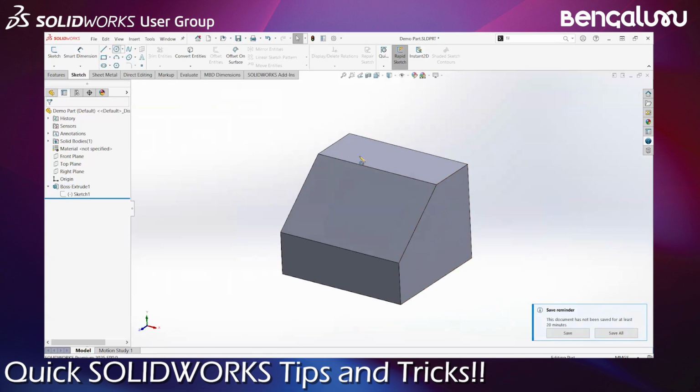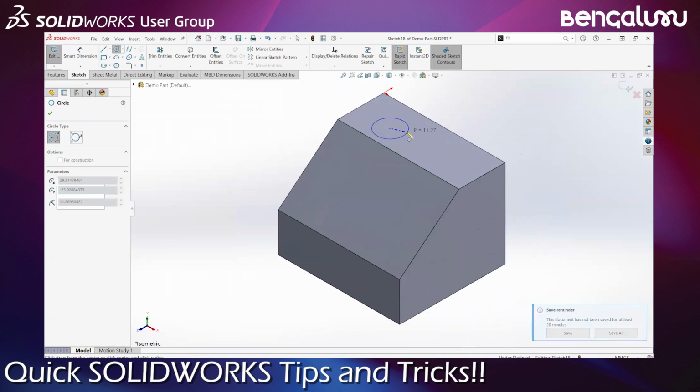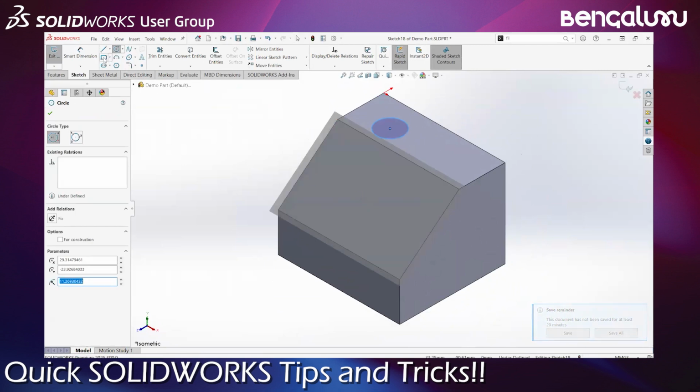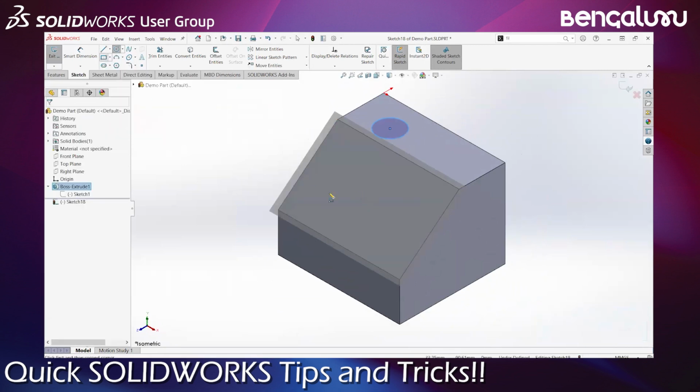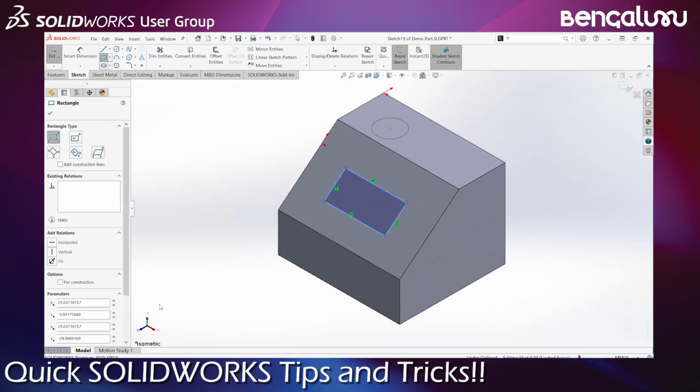So what I do, for now, is keep it back in isometric view. On this face I need a circle, so I quickly draw it. On this face I need a rectangle. I select the rectangle tool, and once I hover over the face, I can simply start sketching it. Then on this face maybe I want a slot.